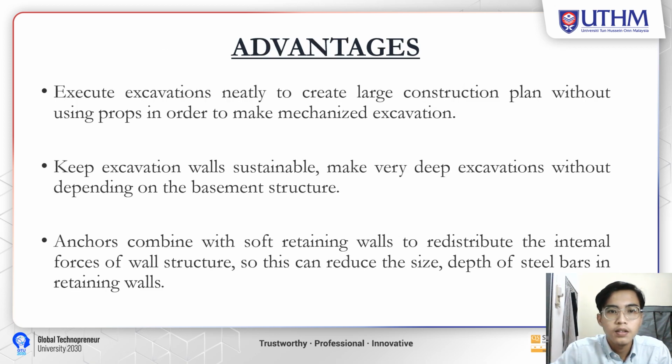Next, there are several advantages of ground anchor. Number 1 is to execute excavations neatly to create large construction plans without using props, in order to make mechanized excavations. Number 2, keep excavation walls stable and make very deep excavations without depending on the basement structure. And number 3, anchors combined with soft retaining walls redistribute the internal forces of the wall structure. So this can reduce the size and depth of steel bars in the retaining wall.